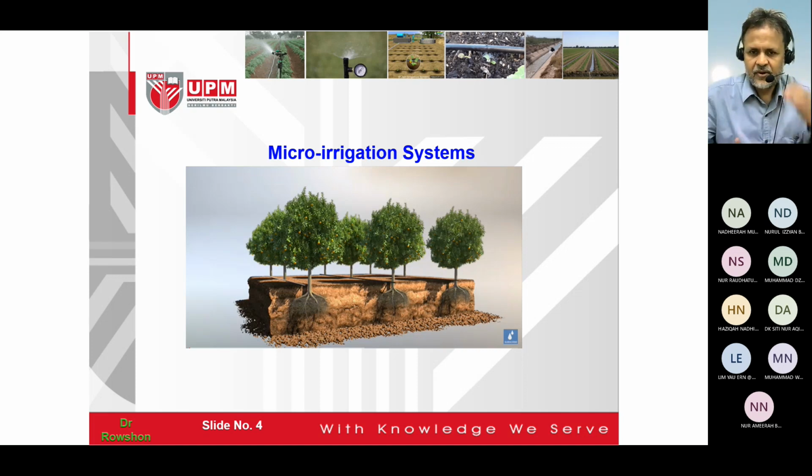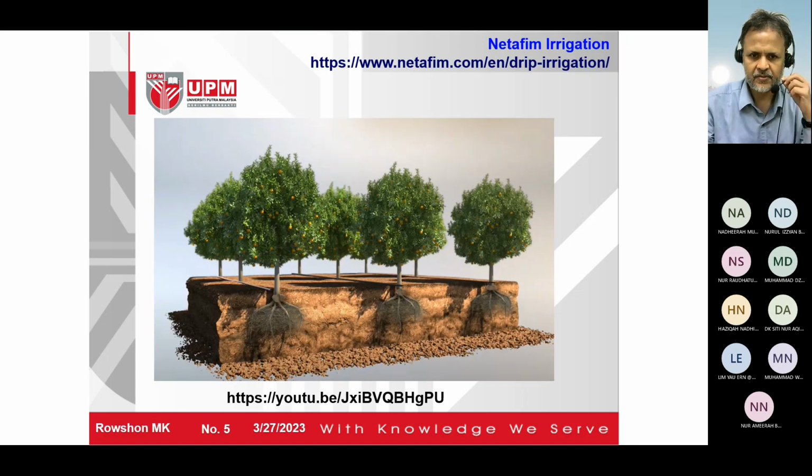So as I mentioned, for any irrigation system, when you want to design it, or develop irrigation scheduling, or supply water, the first thing you need to do is the crop water requirement. So this is the crop water requirement. This one you have seen already. Maybe here the picture is a little bit wider and clearer, so you can see the rows.